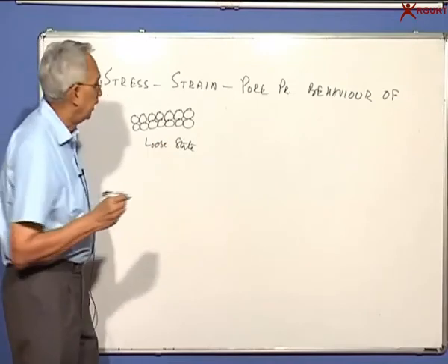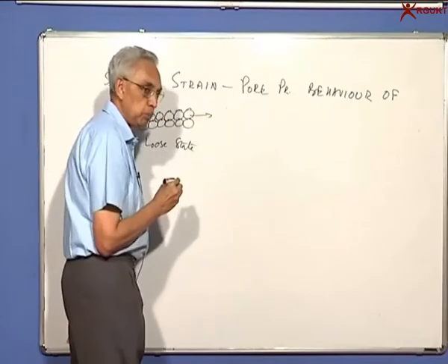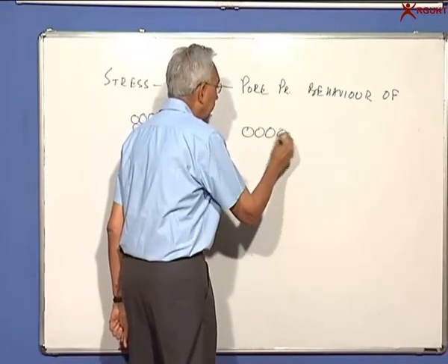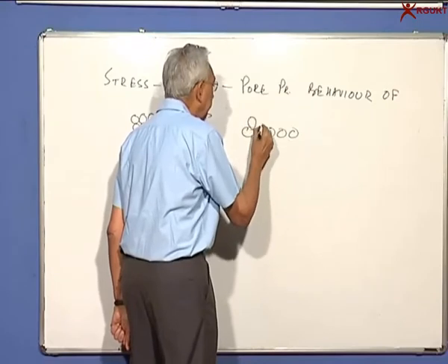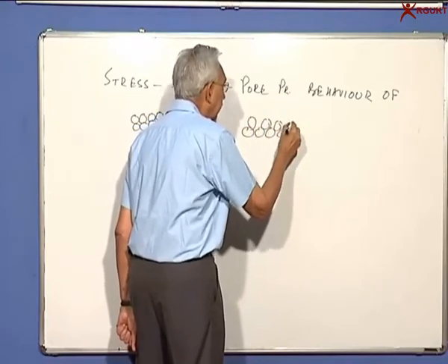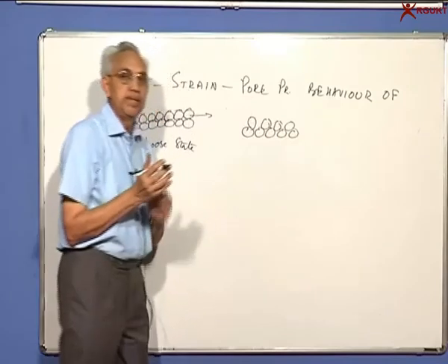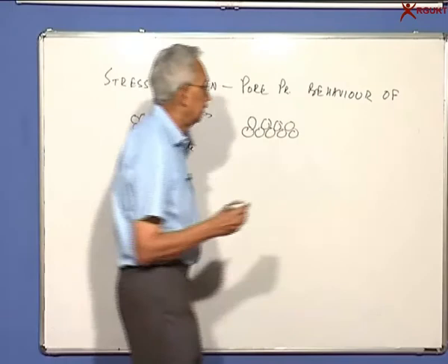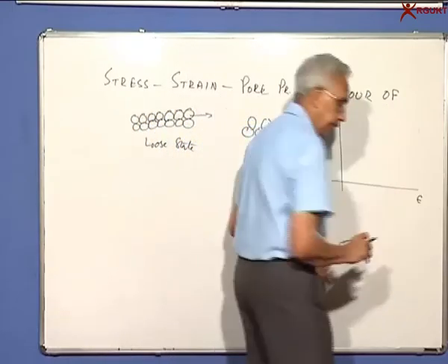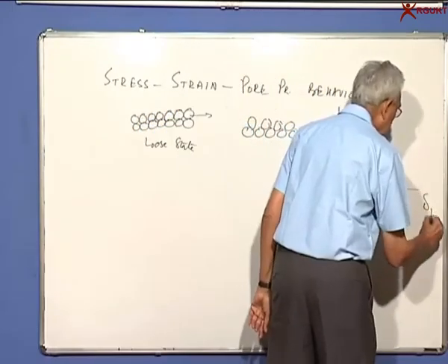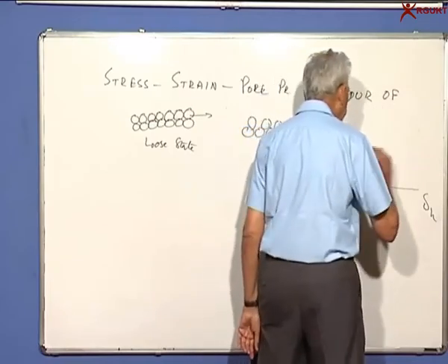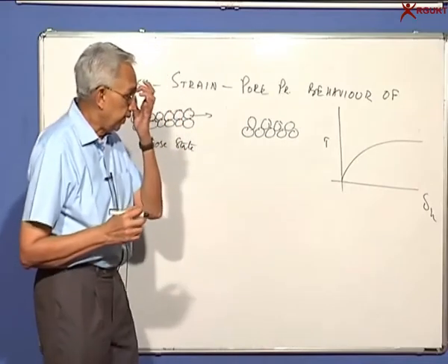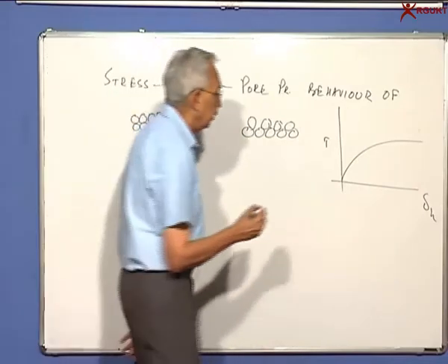Now you try to shear, then what is happening is these particles in the upper level will try to roll into the lower level. So the soil during the test is getting densified or getting compressed. So when I was plotting this graph, delta H versus tau, what it's trying to do is trying to adjust so that it will get to a state of packing which is finally the equilibrium state.